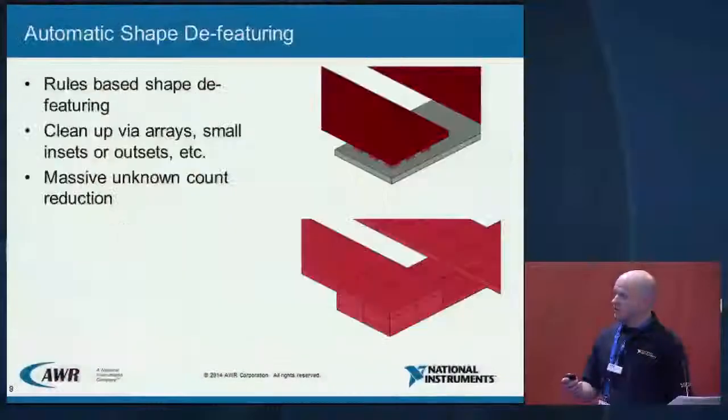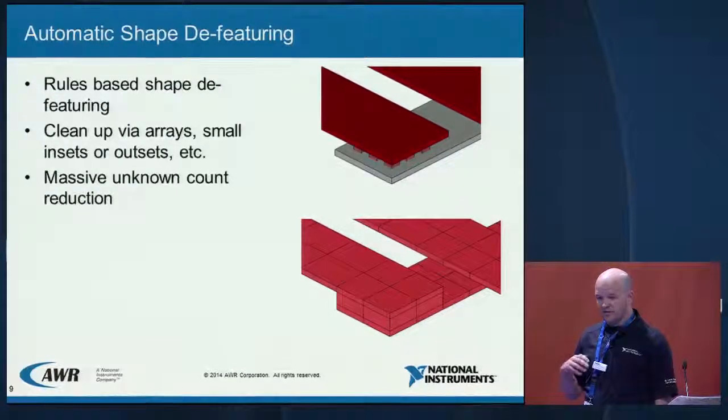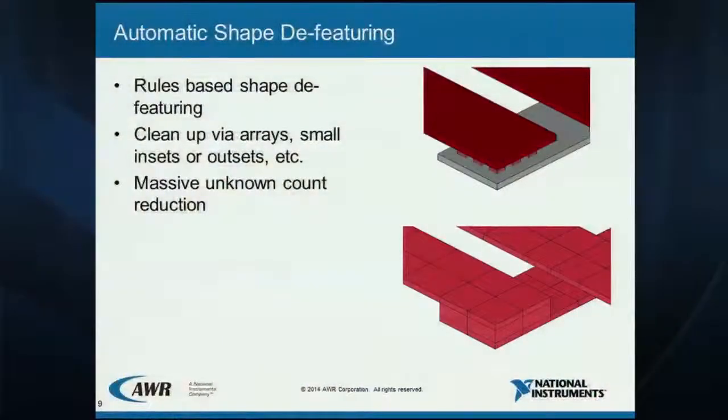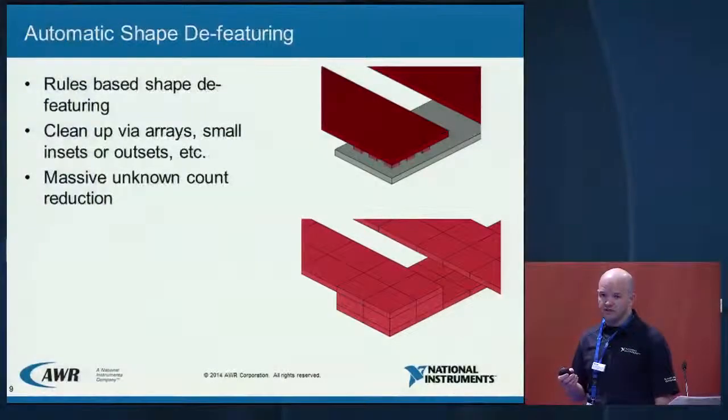One of the really nice things about our EM environment, and this is not specific to the simulator, that's something that's handled in the UI, is this automatic shape defeaturing that we have. This means different things for PCB. In PCB, it could mean converting circular vias to hexagons or octagons or squares. In a GaAs IC or GaN IC, it could mean converting like I-beam metal stacks into just straight up and down metal stacks. But in RFIC, we always have a problem with the vias.